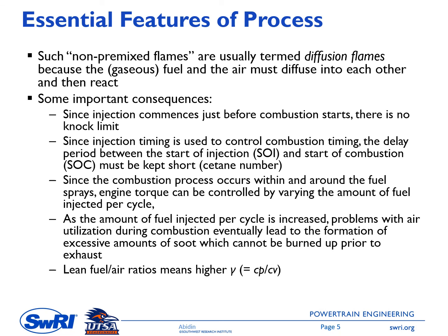So this combustion process occurs under non-premix combustion, or a non-premix mixture. Because the fuel is injected right before the piston hits top dead center, it will mix right away, and then the combustion will occur right after the start of the injection. And there is an ignition delay there.